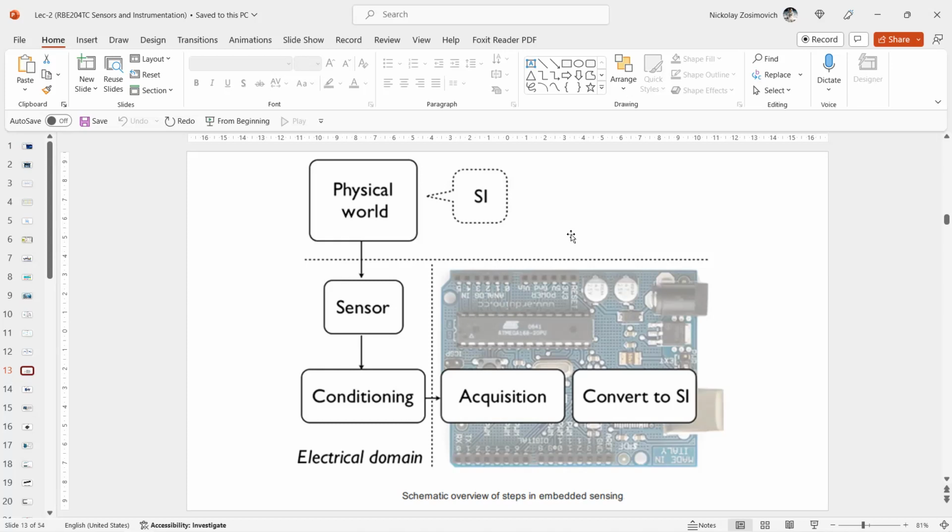So, when eventually a voltage is generated that has a linear relation, which is preferable for us, or at least changes with the measurement, the signal in the electrical domain can be considered, and it can be converted to the digital domain, typically with an ADC. Okay? For further processing, and finally visualization and interpretation.